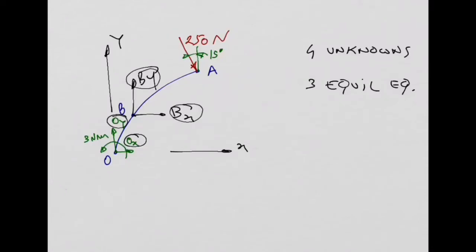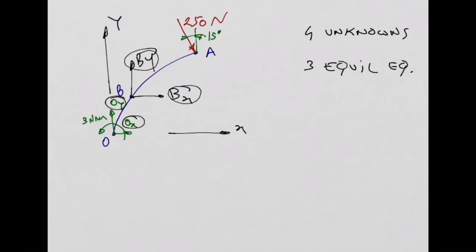Okay? So what do they have to do in order to solve this problem? Well, if they want to use this approach, they can do it, but then they need to do another free body diagram for the strut, right? For the cylinder, BD. And then at point D, if I have this BX, a force to the right, in the strut it's going to be the reaction which is going to be pushing to the left. So you need to basically put the same BX here, but pushing opposite with this BX, right? Action-reaction, or Newton's third law.